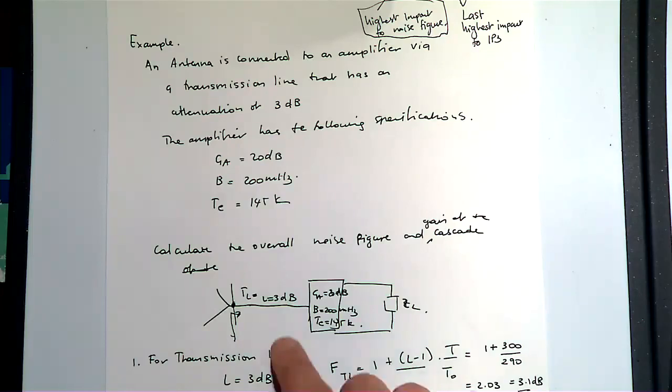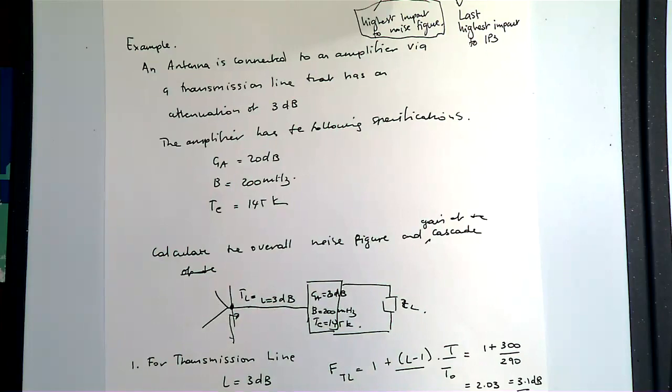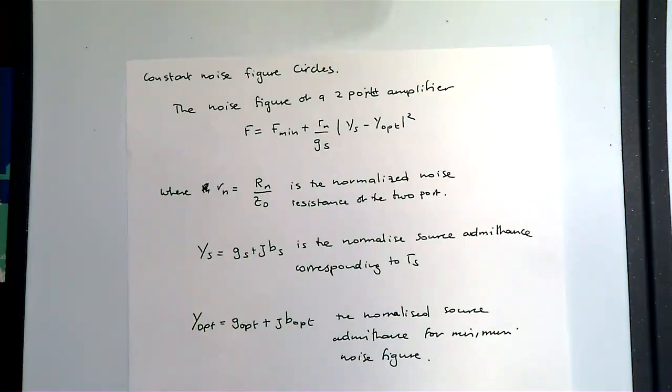And the reason is not only because of the noise figure introduced by the loss, but also because it causes amplification of the noise figure of the following stage. Okay. So that gave us some system level insights into transceiver design. Now, what I'd like to move on to for this lecture was, we've gone through stability circles,